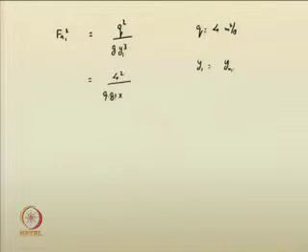You just find the Froude number in the upstream portion. You remember that the Froude number squared is nothing but q squared by g y1 cube. I have q equal to 4 meter squared per second. So, 4 squared by 9.81 into y1, which is nothing but your normal depth in the upstream portion, 1.1, to the power of 3. I am getting the square of the Froude number as 1.2254.